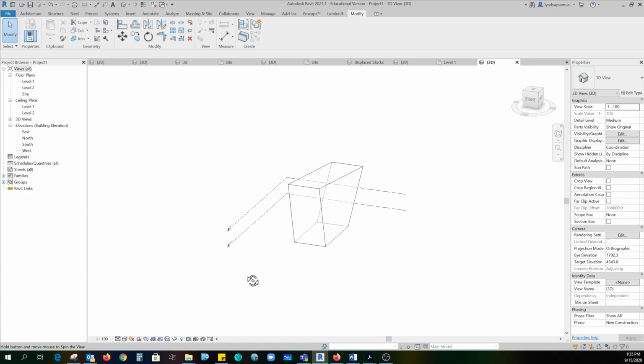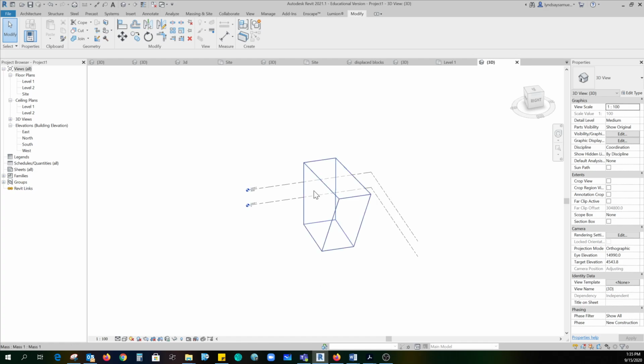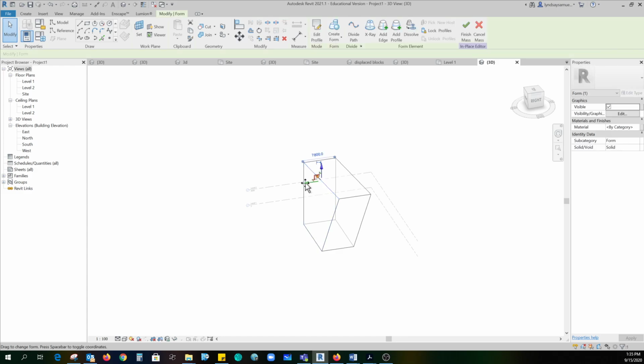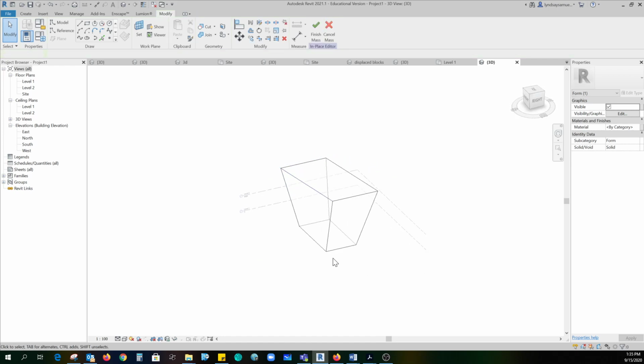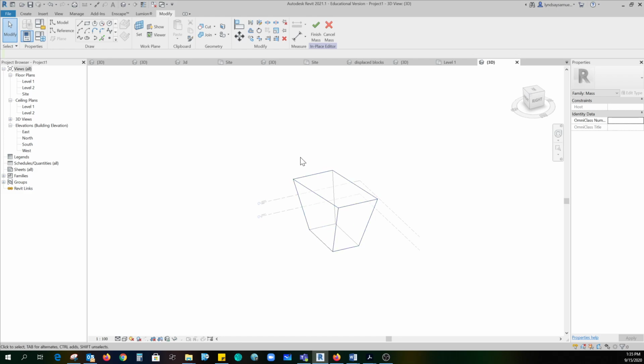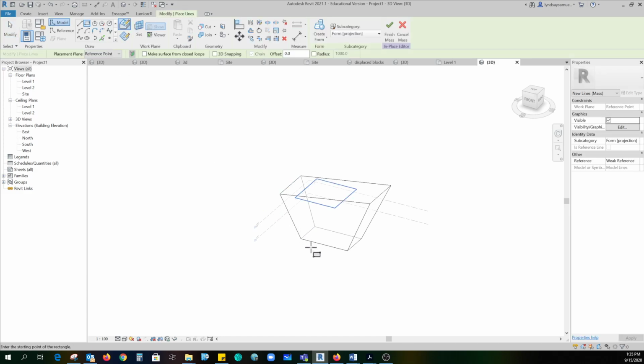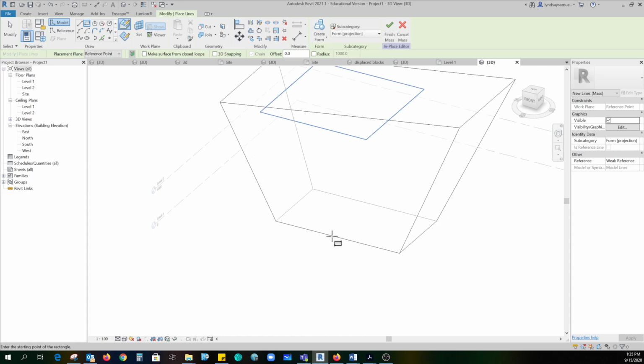All right, I want this building to kind of lean out a little bit more on all four sides. So I'm going to grab that edge and drag that guy out. See? All right, I'm still in the editing of that shape. Now I want to kind of carve into this where, if this was my building, I want to have kind of like a covered entrance. So I'm going to go back to create, and I'll use another rectangle. And I'm going to just draw a rectangle right here like this.